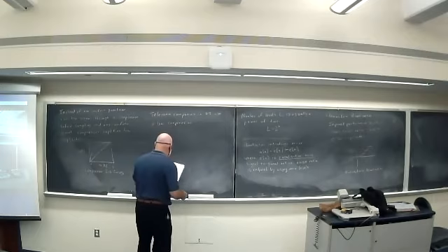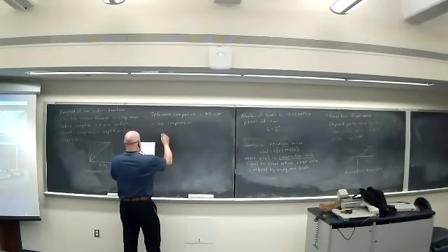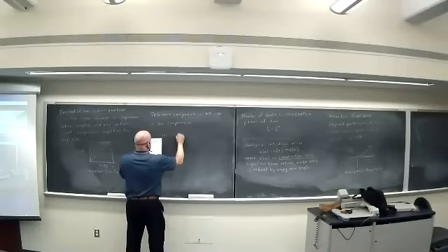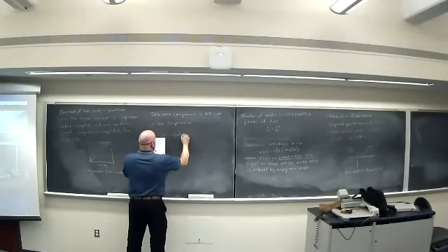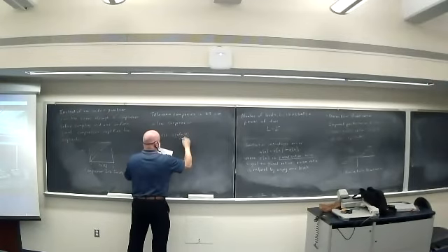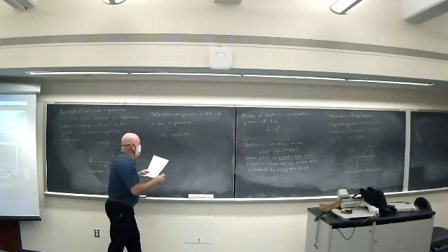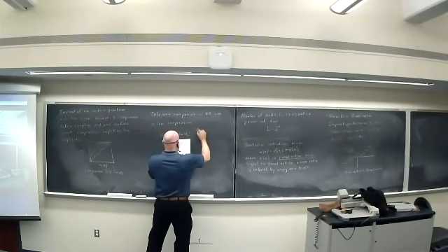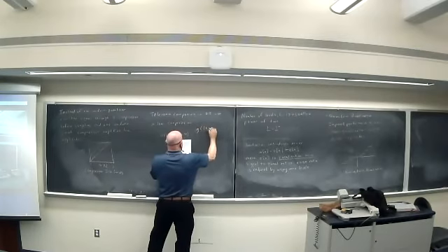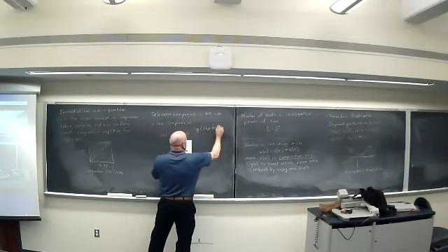So this mu-law compression curve: the sign of m(t) here is just to preserve the sign. You'll see that the expression involves the absolute value. It's the log of 1 plus mu times the absolute value of the input, over the log of 1 plus mu.